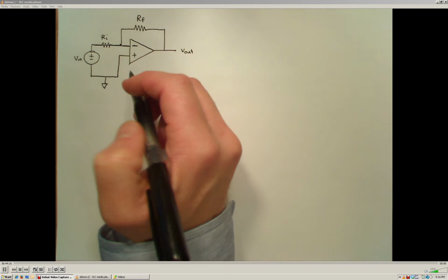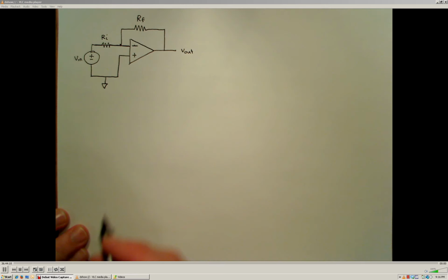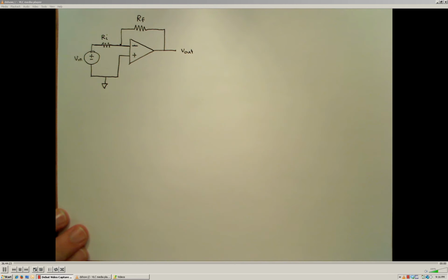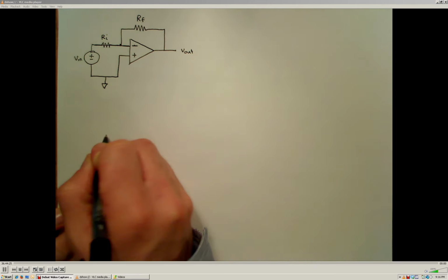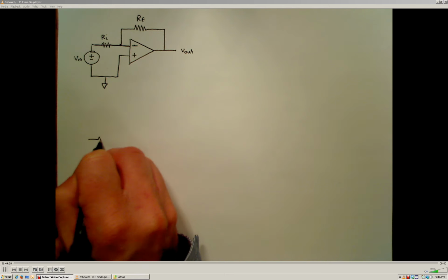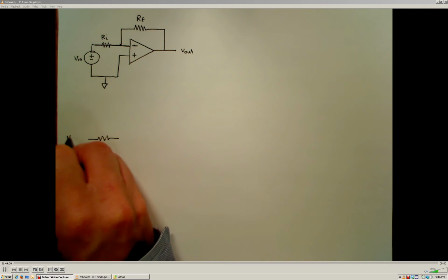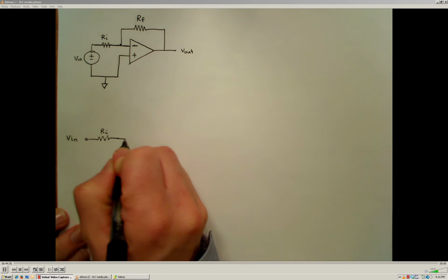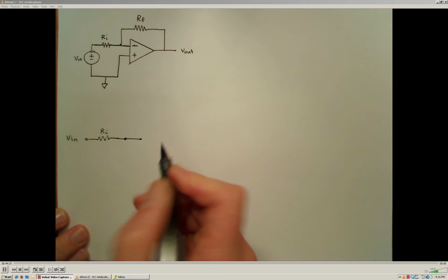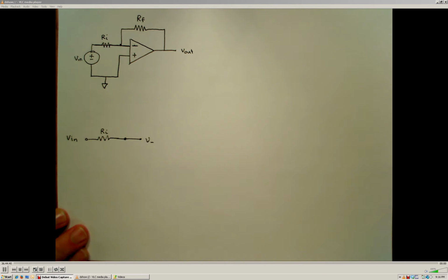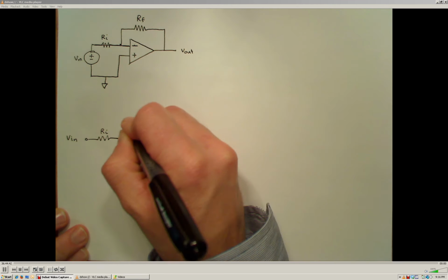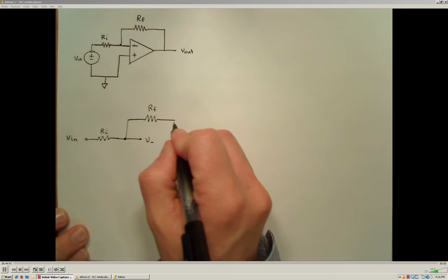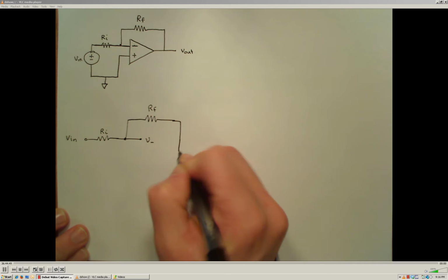resistor. Okay, so now let's use the ideal op-amp model to look at what is the expected behavior, the voltage output behavior of this system. Alright, so again, with the ideal op-amp model, we're going to have Vn through the resistor Ri, and that's going to go into the inverting input terminal, V minus. I'm also going to have that connected to Rf, and that's going to be connected to V out.